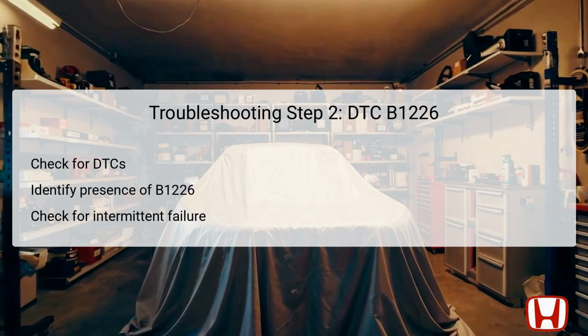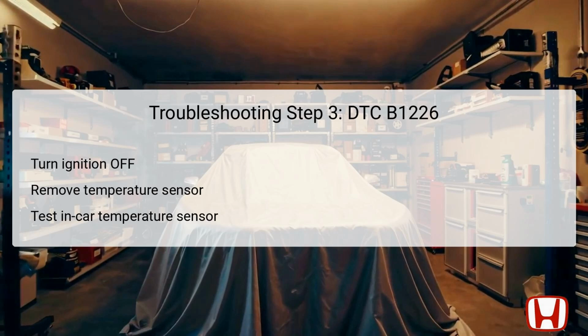This might require visual inspections of the connectors and wiring along the length of the circuit to ensure that there are no loose ends, fraying, or other visible damage. Establishing the presence of DTC B1226 will guide the technician on whether to proceed with further testing or focus on potential intermittent faults.